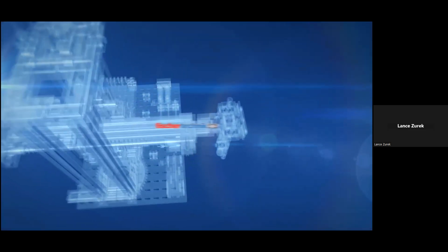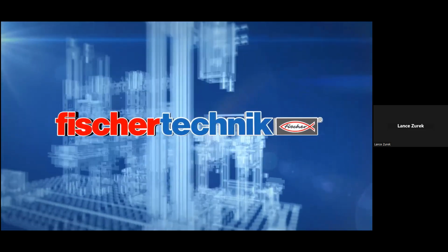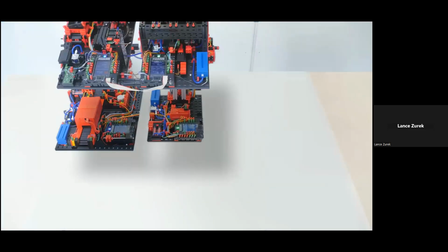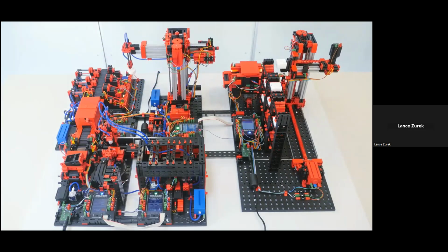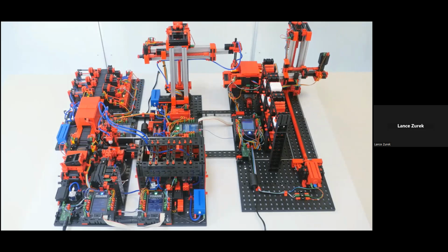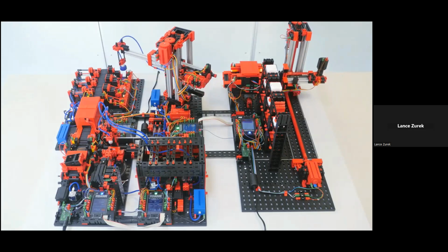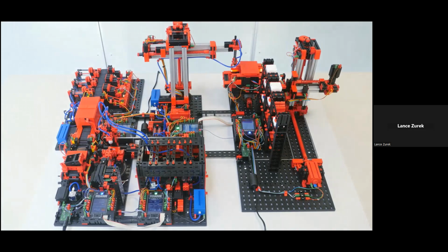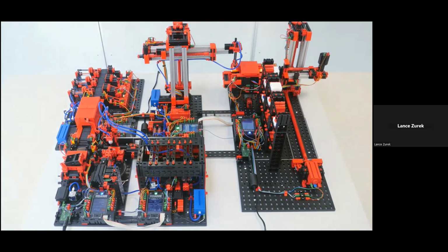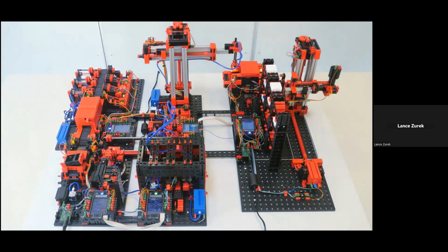And the cycle that you're going to see in the video works like this. Work pieces get retrieved from the automated high bay warehouse using the vacuum gripper robot, and then they are moved to the multi-processing station with the oven. Now, after the workpiece has been processed by the oven, it is then sorted by color in the sorting line with color detection before again being moved by the vacuum gripper robot back to the automated high bay warehouse for storage. Now, as we've already discussed the components of each of these individual substations previously, I'm not going to belabor it by restating them here.